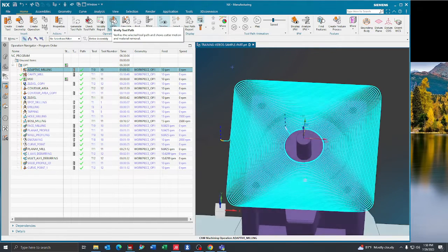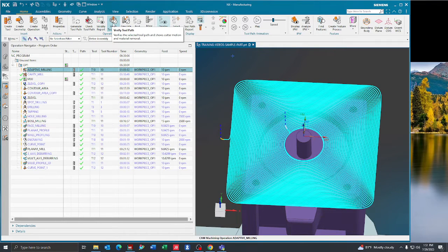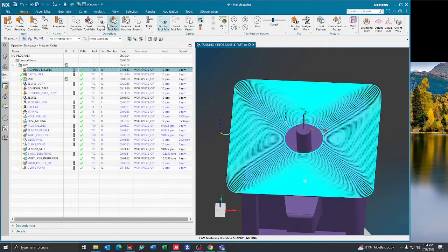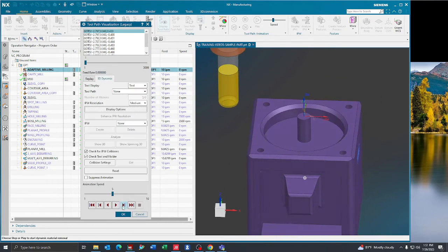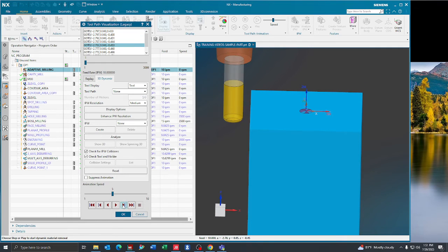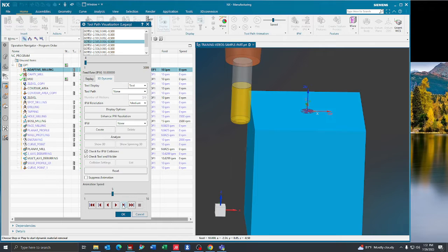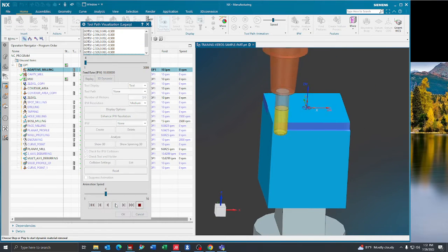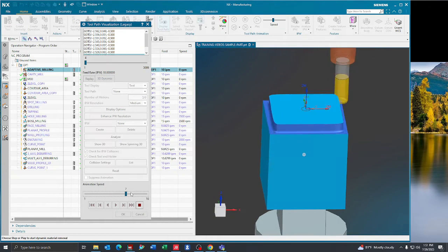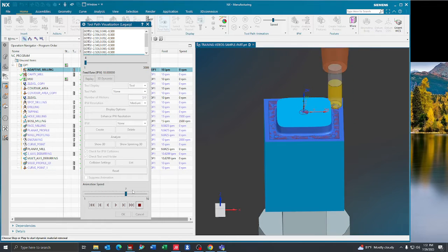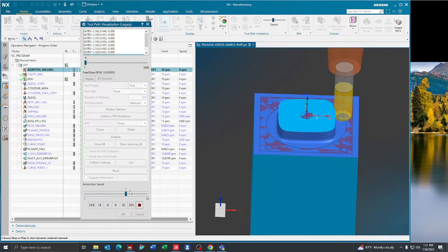So there's our toolpath. You can see it drops down off of the work, and then it's just going to, in an adaptive style, high-speed machine its way into the center. If we verify this here, it's going to start off the work. As we step through, it's going to lead in, and then just slowly high-speed machine its way into this boss.